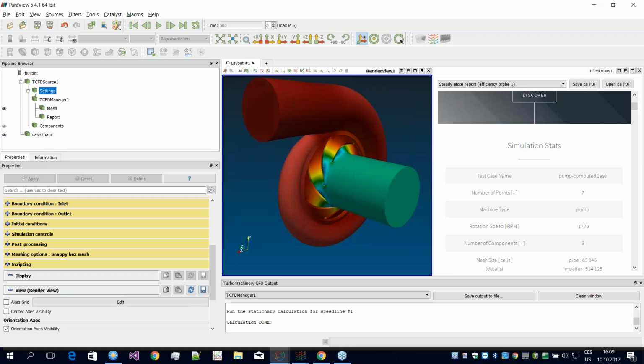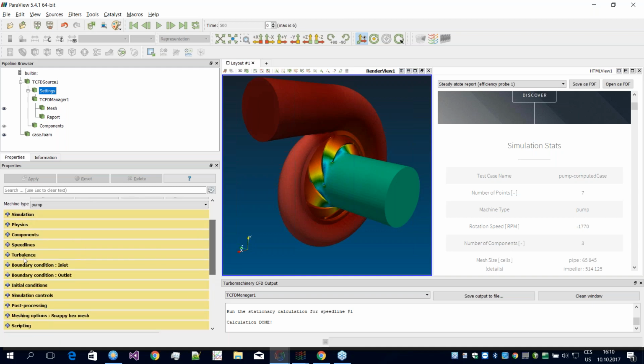Okay, so if you mean the fully structured or block structured hex mesh, it's not. We are not able to do that with the snappyHexMesh tool, which we are using. It creates the dominant hexahedral mesh, but let's say, it changes the shape of the hexas like tetrahedras in the neighborhood of the surfaces. But there is an option to add layers.